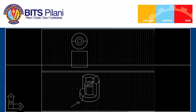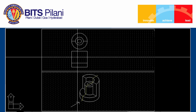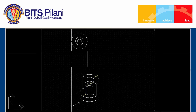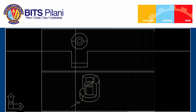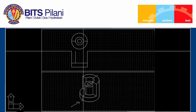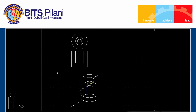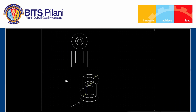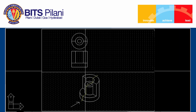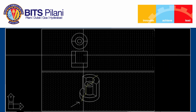This principal surface I can draw, which is having height 2, and these two principal surfaces you can see here. Okay, and if you see, this principal surface will fall into a line view that I can draw here. From the top, 2 grid space down, I have to draw a line.